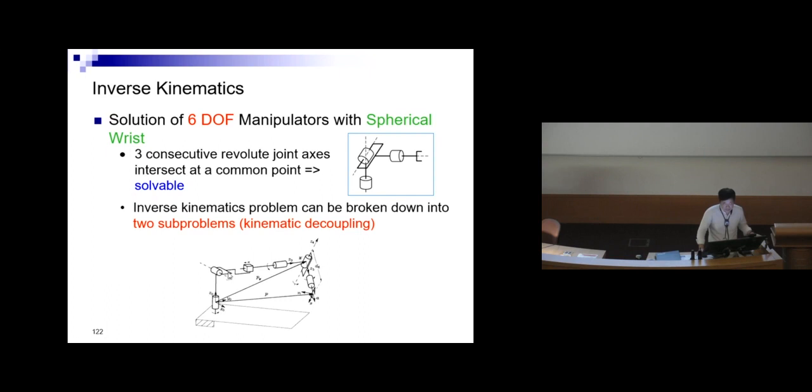So this is a manipulator that we looked at earlier on when we first derived the DH notation. This is the base and a revolute joint, so this is one joint. This is a prismatic joint, and then you have another revolute joint, and another revolute joint. You define your wrist point over here. So this is your end, and this is your wrist point.